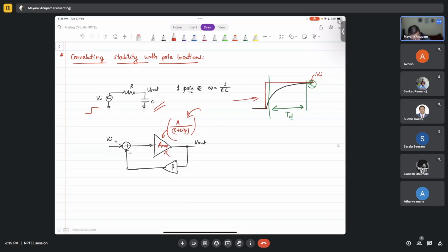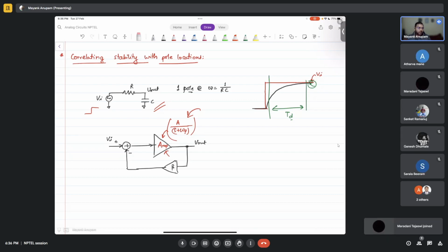Nothing else. Okay. So in the presence of poles in the negative feedback system, there is a possibility that the system becomes unstable, because poles manifest themselves as delay in the system. Now it turns out that if the system has one pole, no pole, or two poles, the system will always be stable. That comes out from another thing called the Nyquist stability criterion. If the system has up to two poles, it will never become unstable. So such a system can be called